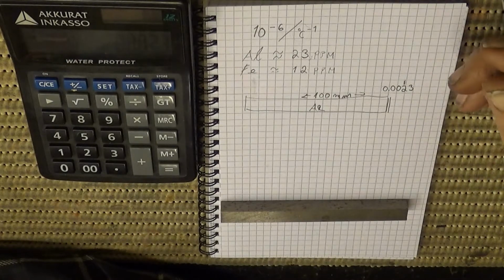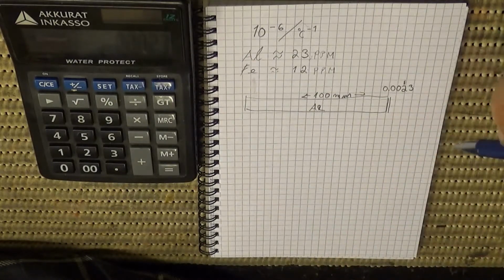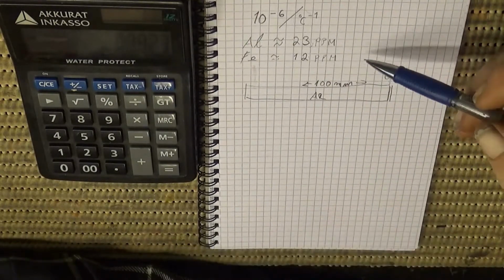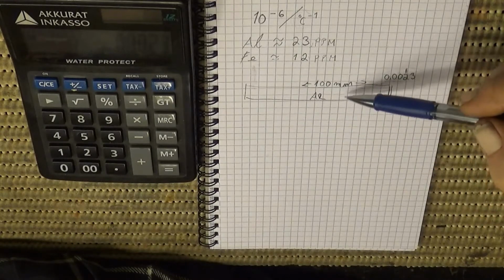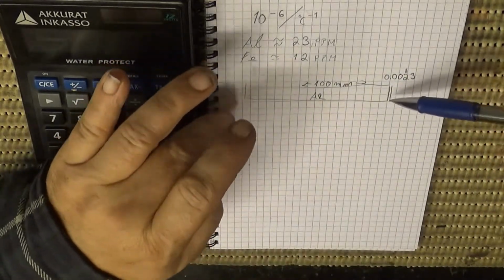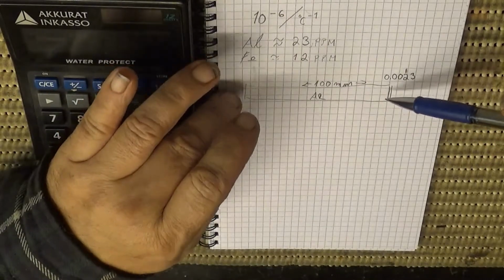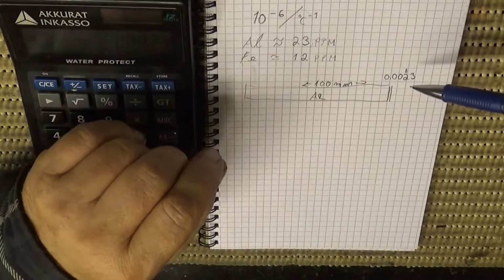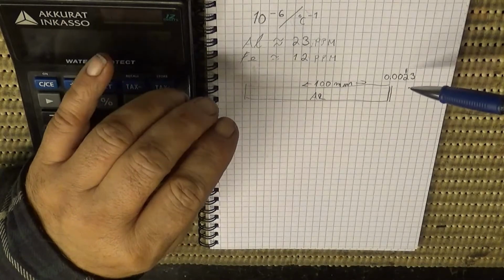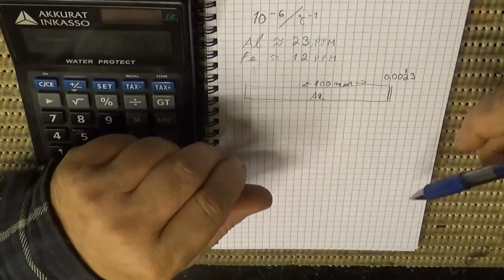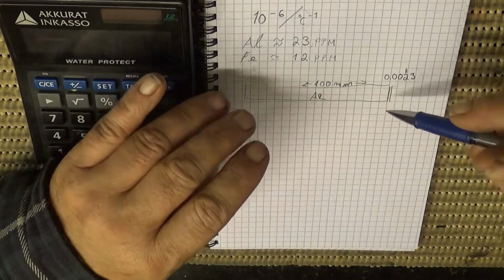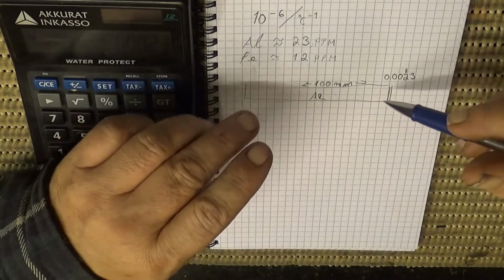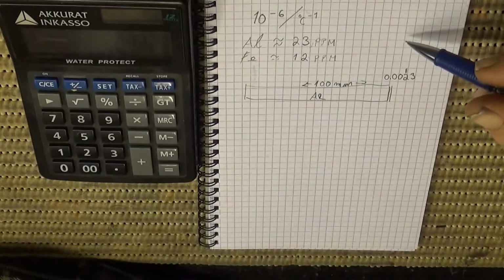Okay, and so on. So basically you could measure temperature just by measuring the length of a known object, at a known temperature, of a known material, etc. And then of course you have to compensate for your micrometer, which is also made of material, which will become larger or smaller depending on the temperature.